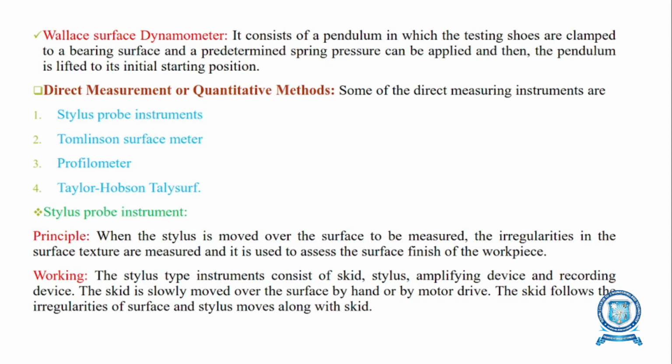So the direct methods enable us to determine a numerical value of the surface finish of any surface. These methods are quantitative analysis methods, and the output is used to operate the recording or indicating instrument. Direct instruments are operated by electrical principles.